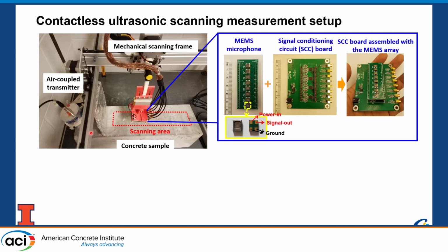Here's the sender. The surface waves are propagating here, and then this is a multi-element array here, and we just scan it, and we collect lots of data at every half millimeter or something like that. And we collect them across cross-section. So one scan here, and then we can move over and scan another one, and move over and scan another one, and then we have a 2D plane.